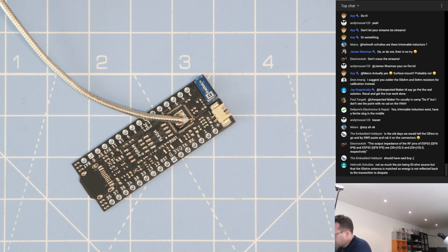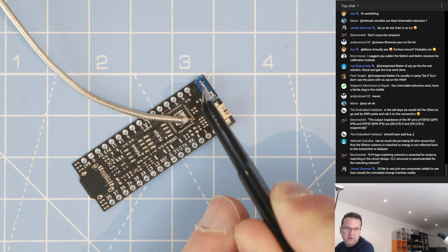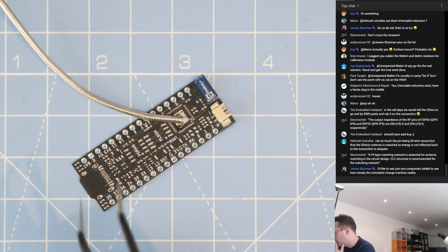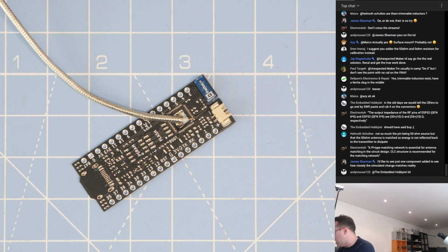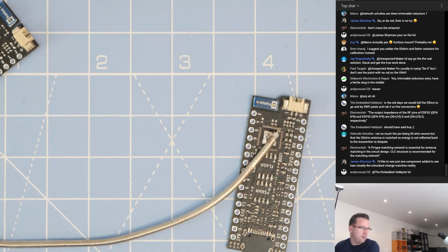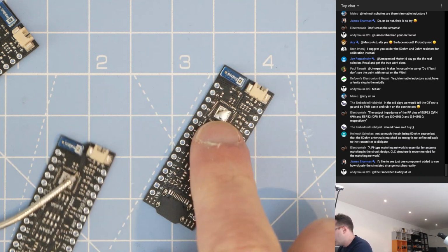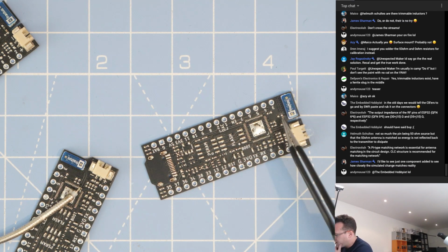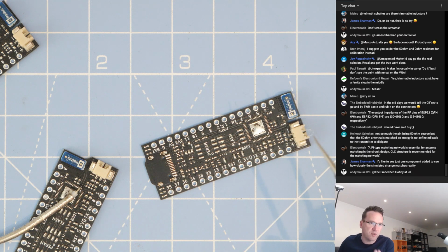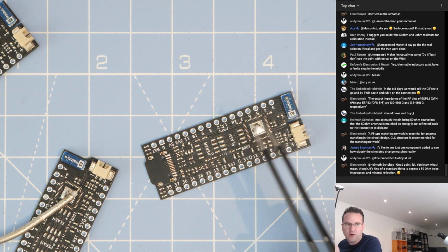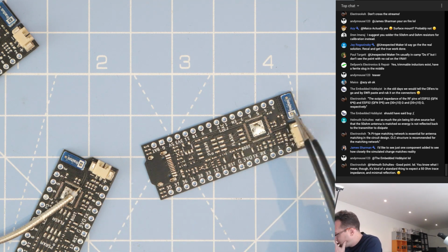so right now, I'd have to take the antenna off, right? Let's assume I'm going to calibrate on this board, or on another board. This is the one that's got no matching network. So I can take this feed line off here, and I can take my other one that has a matching network, and I can put the feed line on here. So I need to take the antenna off, and I need to do a version. The problem is I need to resolder these boards in between each time, right? Ideally, this is going to be a pain in the ass, and I'm going to risk knocking the antenna feed line off each time.